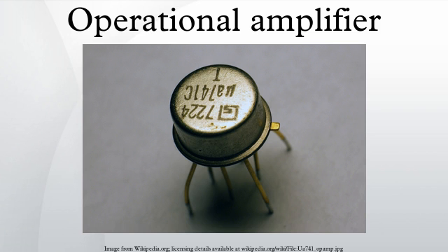Differential amplifier: a cascaded differential amplifier followed by a current mirror active load. The input stage is a transconductance amplifier, turning a differential voltage signal at the bases of Q1, Q2 into a current signal into the base of Q15. It entails two cascaded transistor pairs, satisfying conflicting requirements.